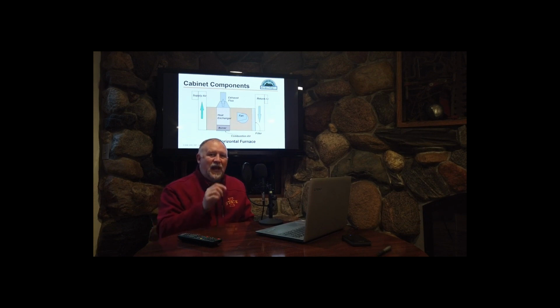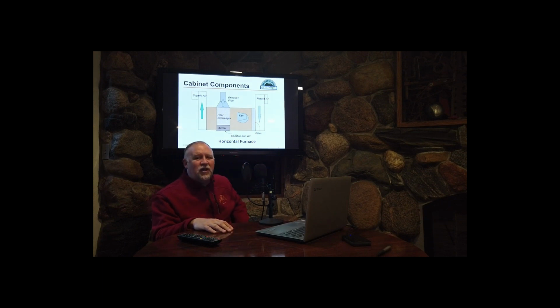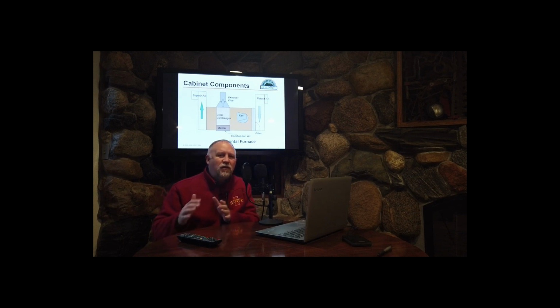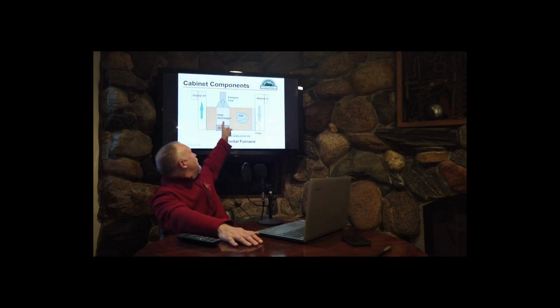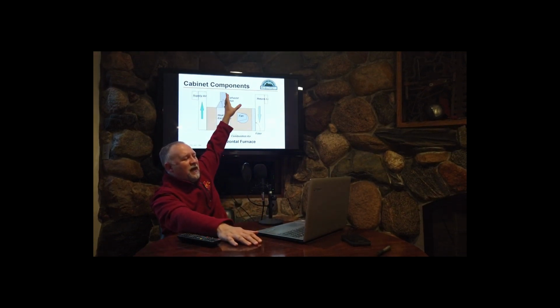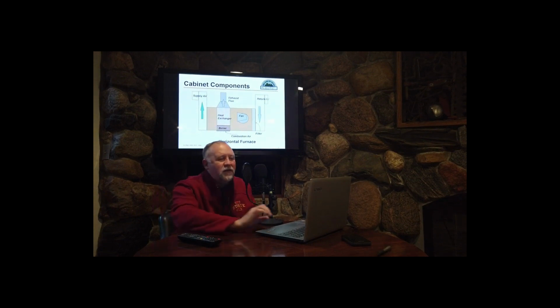If there is a failure of the heat exchanger, like a crack in the heat exchanger, that is a very, very major failure, because now the deadly carbon monoxide can get into the people space. That is why if you have a natural gas furnace, you also need a carbon monoxide detector. So anyway, the exhaust stuff goes up the exhaust flue and outside. The now warm supply air goes back to the room.